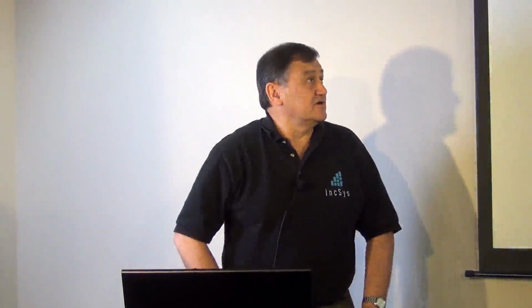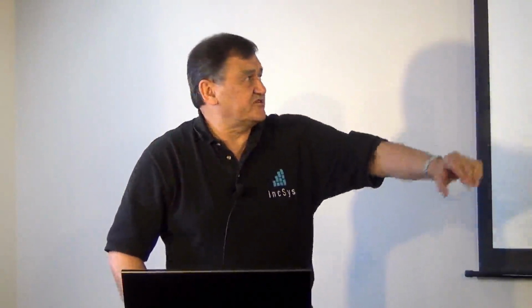All right. So we've touched on this at different parts, but the main causes of low voltage are that you've got a deficiency in reactive power. Your sources of reactive power are hitting their limits. And so as you don't have that reactive power available, the voltages start to sag. Heavy power transfers across heavily loaded transmission lines cause the reactive power absorption of those lines to go way up.